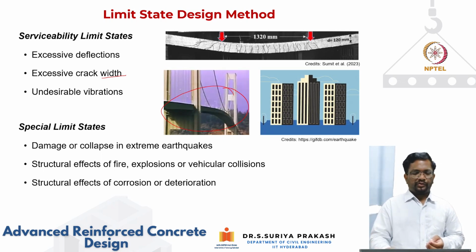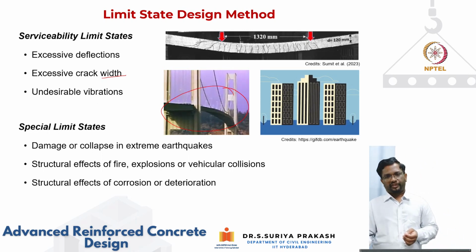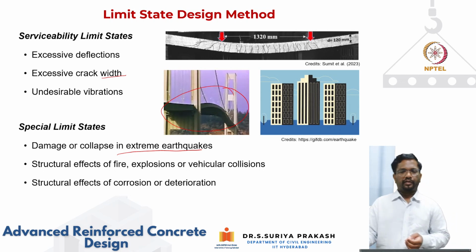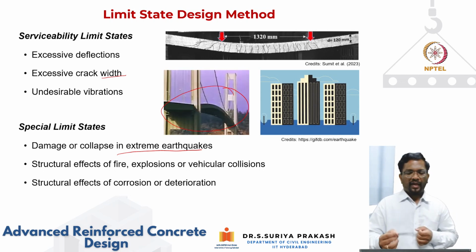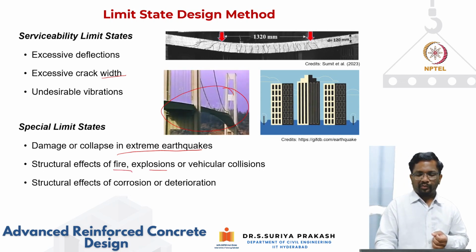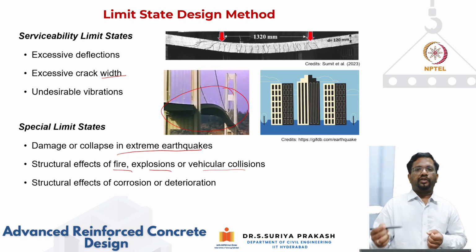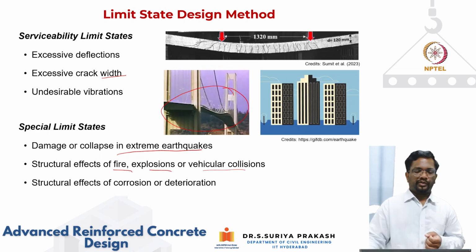And sometimes we also check for special limit states. Damage or collapse in extreme earthquakes will come under special limit states. And structural effects of fire, explosion, or vehicular collision are also special limit states. And then structural effects of corrosion or deterioration is also one of the special limit states.